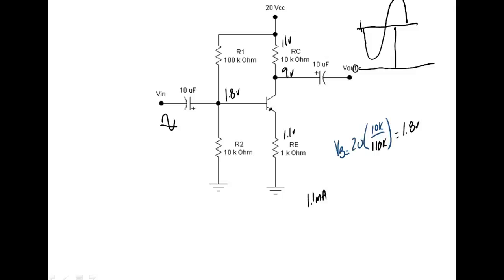So on an amplifier, you can measure the bias voltage even if it's active. Because even if it's sound, and it's all over the place, so sound looks like this, it's all over the place, but still it's going to average down the center. For every one going up here, we have the other one coming down here, right? You understand? So you can measure the bias voltage with it playing loud open.